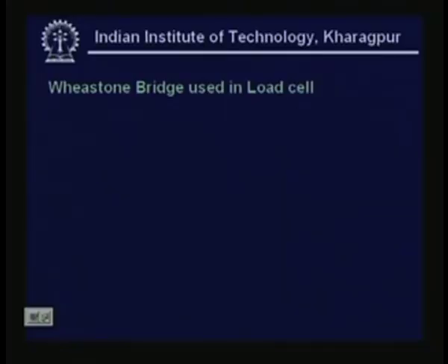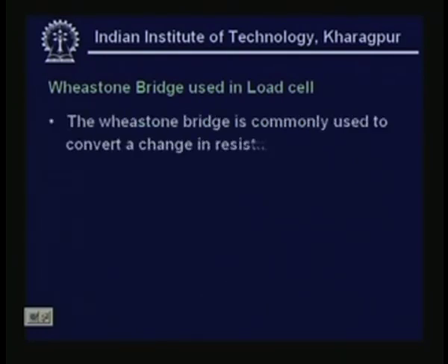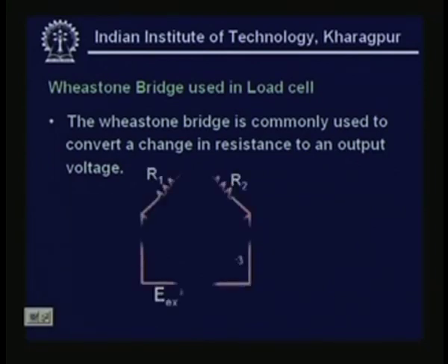Now, as I told you, you will use basically a Wheatstone bridge in the load cell. The Wheatstone bridge is commonly used to convert a change in resistance to an output voltage, that we have seen in the case of the simple balanced Wheatstone bridge. So, here we will use the unbalanced Wheatstone bridge.